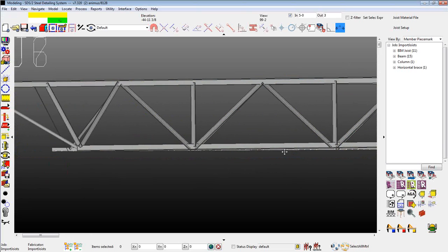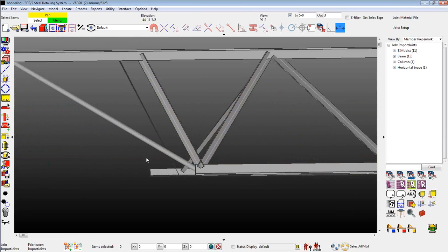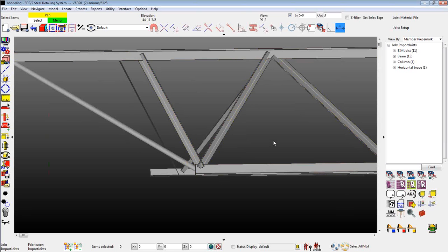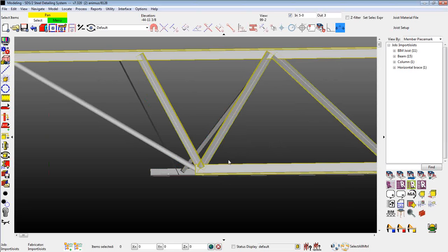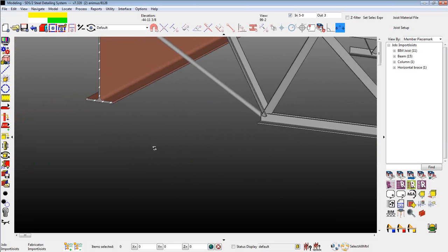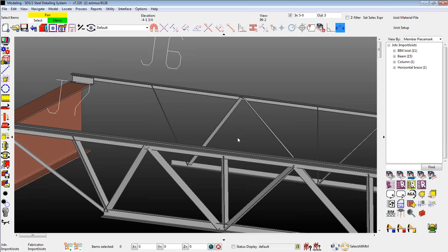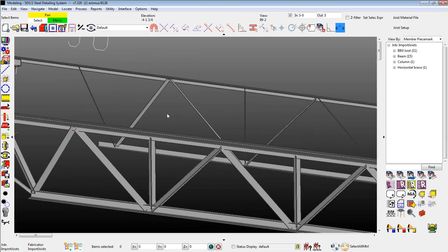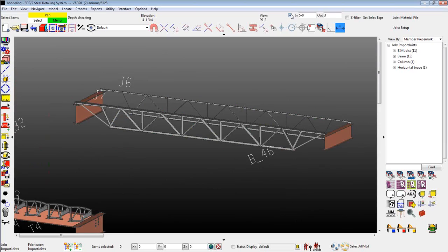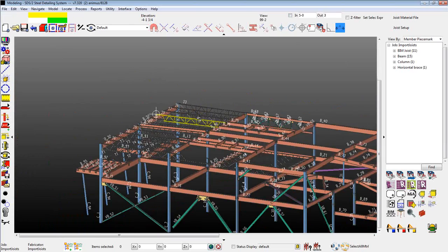This goes back to showing you that the pre-configured panel layout uses a worst case scenario where some of that material might be larger than what Vulcraft might design with. So with the as fabricated ones, a lot of times you get a little bit more efficient joist. So just something to watch out for there.